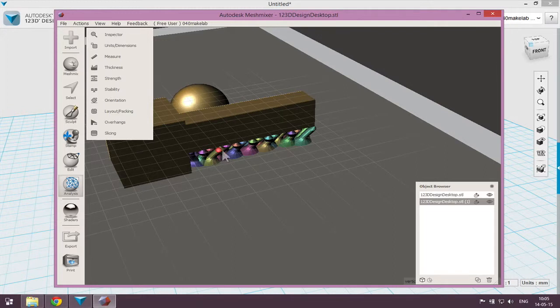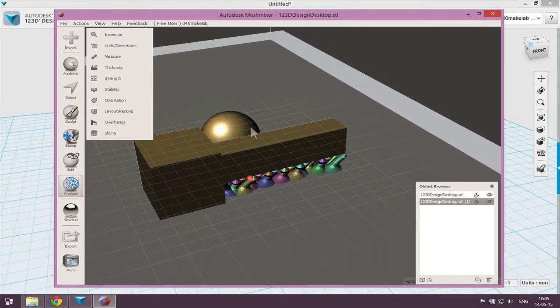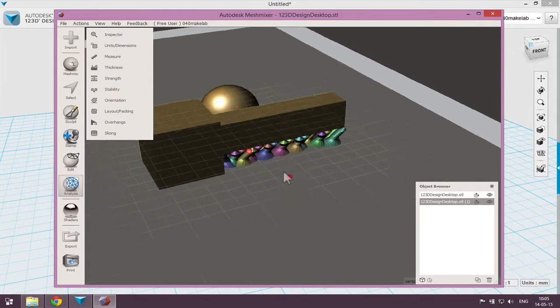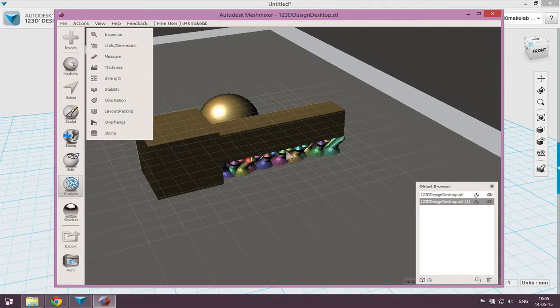So a 3D printer needs this material, it needs to print on something. So this is what it did. This is what meshmixer made in order to have this 3D printed. It already was clever enough to put this ball also on the print bed. So that already worked. And this is called support material from the 3D printer. If this is printed on a 3D printer, you need to break all this support material off. And what happens is if you use the normal support material generator from a normal 3D printer, it'll do a lot more material than it would use if you just use this support material.